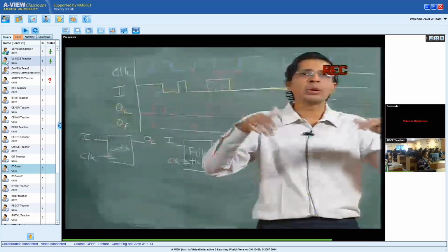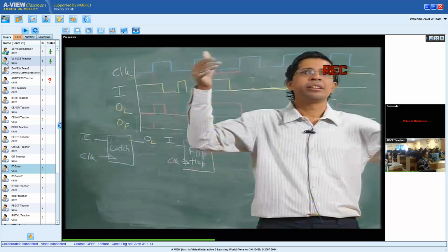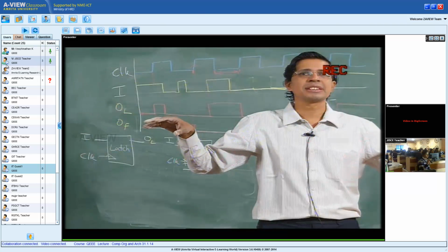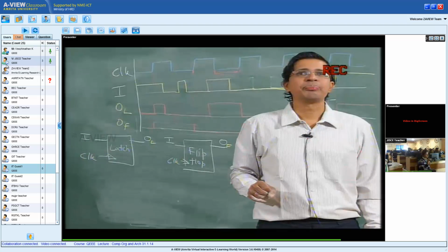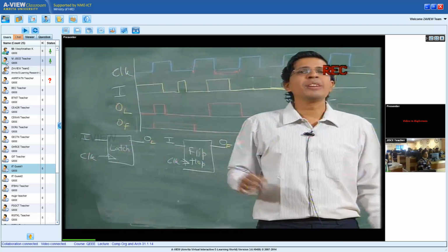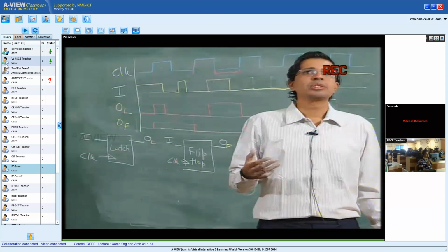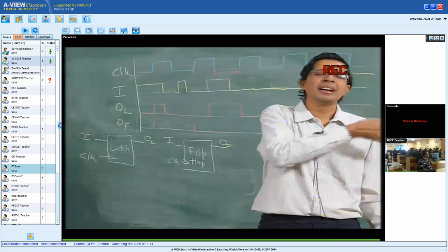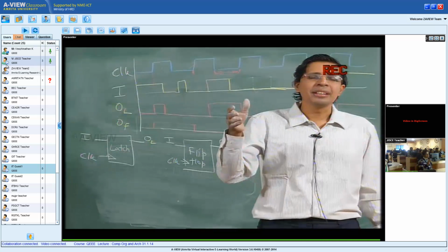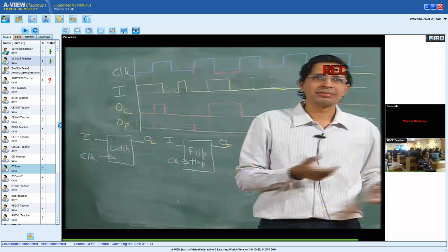So I will store all the 16 bits because I have 16 4-to-1 muxes. 16 bits from the multiplier will come into the mux, and through the mux will come and stay in the register. While for the comparator, I am only interested in 3 bits. So only the first 3 mux inputs will be used. The remaining 16 minus 3, 13 muxes, will be left as don't care.